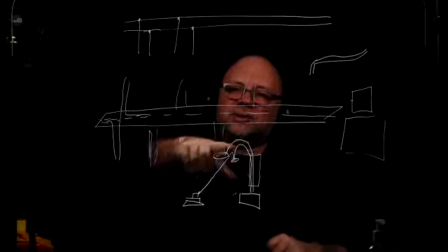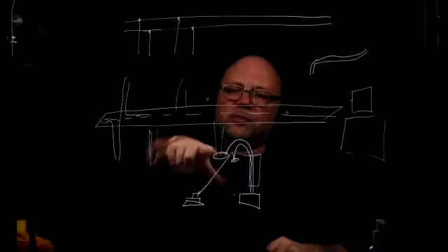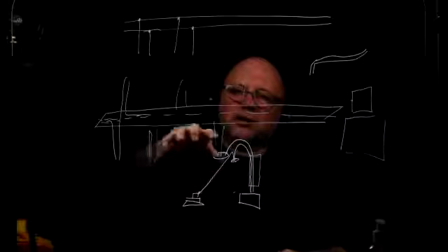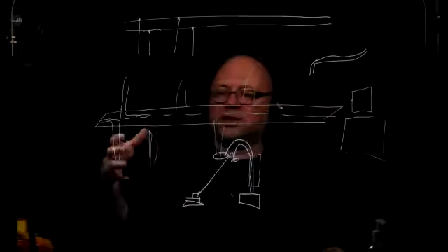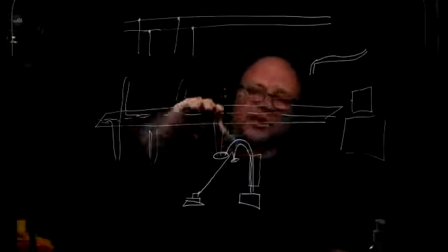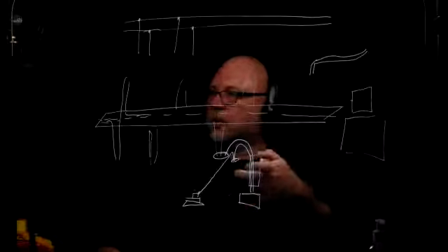And then once all those pigtails are prepared, the two of you can go grab a ladder and just connect those speakers, coil the loop, tuck it in the ceiling, and that 10 or 20 feet of wire is going to let you put the speaker anywhere. It's going to give you the freedom of placing it anywhere in the ceiling tiles that they need to be. And if you need to change it, you just take it out and put it in a different tile. So that's basically the way we're going to perform the lab.